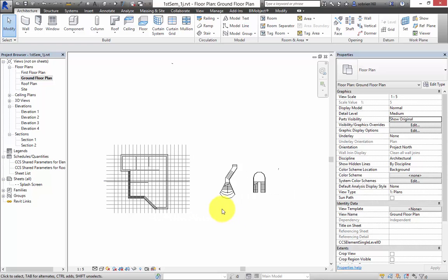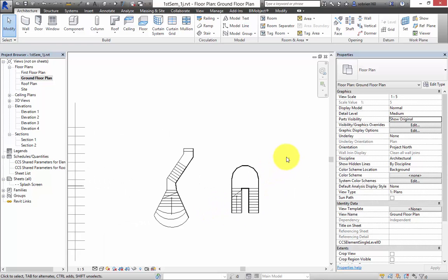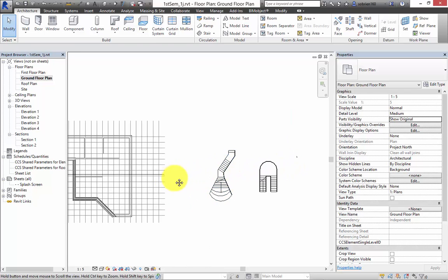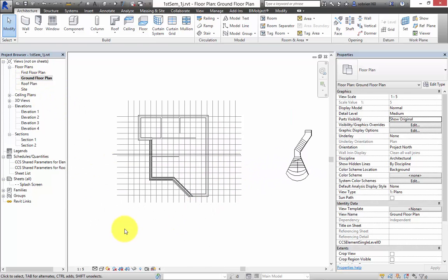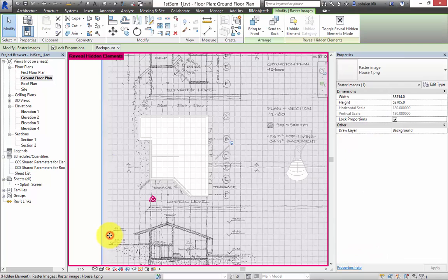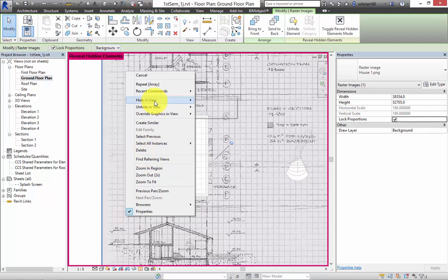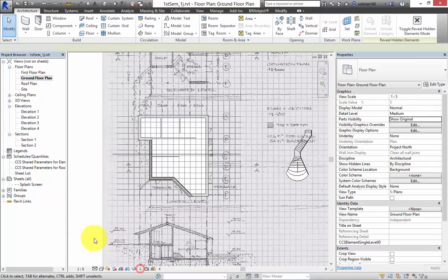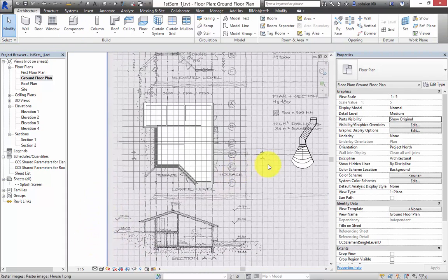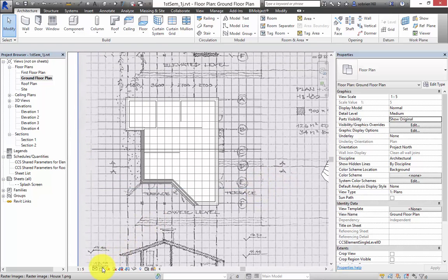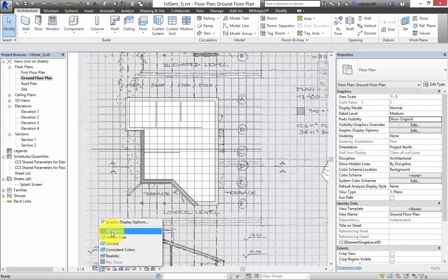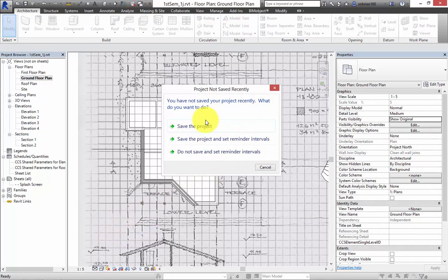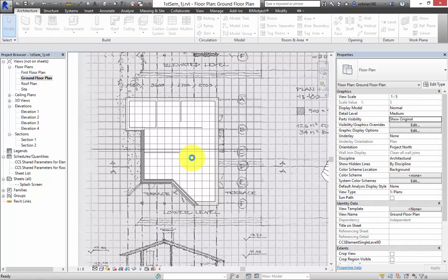All right, so now we've been playing with these stairs, I want to put a stairs in the house. Where did we put it? Yeah, there it is. Let's switch this back on. Now we've got the sketch in the background switched back on. I'm going to turn the view onto wireframe view, so we can see through the building and see the sketch behind.